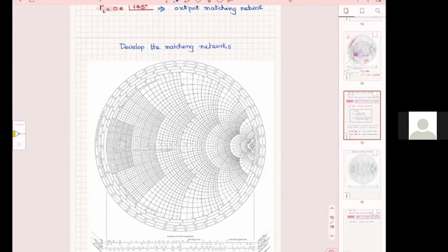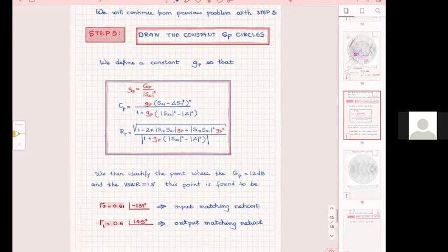I have another question. Yes. So for drawing the lowercase GP circle, how do we find the uppercase GP if it depends on gamma S? Did we just set a value for it and see if we could achieve that? Yes, we said 12, as the lowest. In my case, I did more than one GP. I changed the value of small GP a few times to see exactly what was the highest gain circle that was going closest to the 1.5 dB noise.